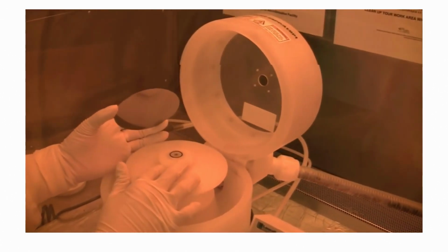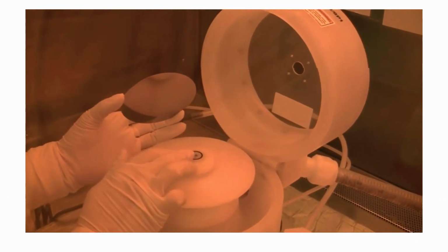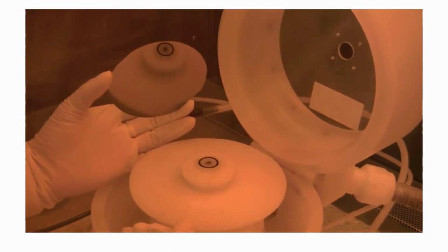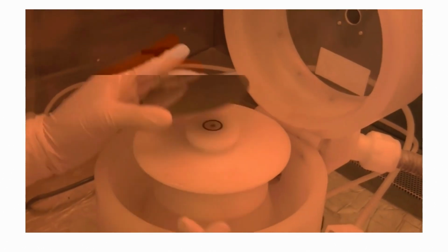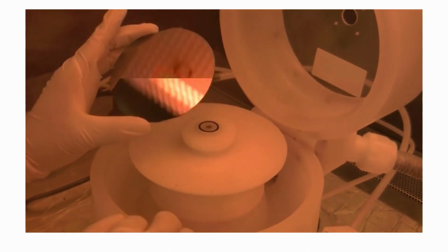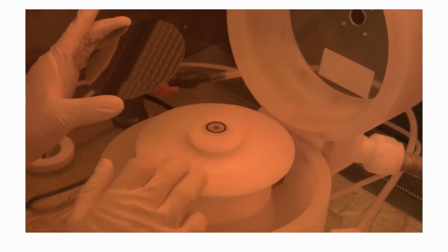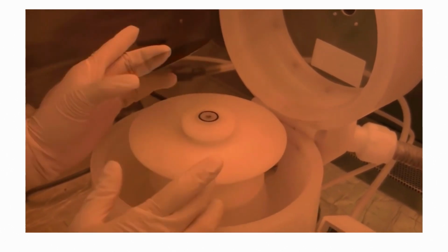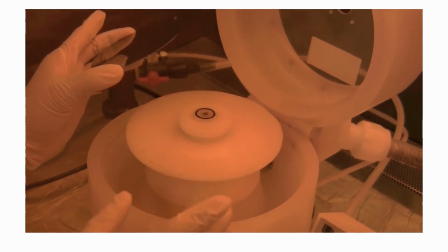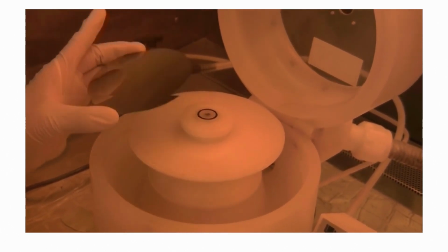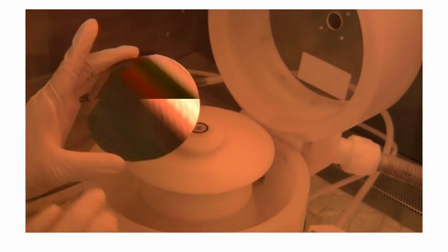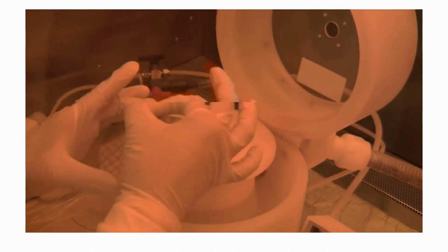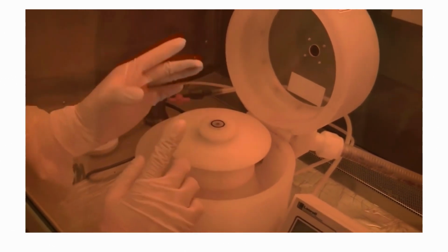So this chuck here has a vacuum in the middle. This vacuum is going to hold the wafer down, so when it spins, the wafer won't fly out. It's very important that your sample is bigger than this chuck. Now if you have a smaller sample than this chuck, that means some air is going to be sucked in around the edges. If that's the case, you must mount your device on a bigger substrate like this. So if I have a small little glass piece, I put it on top of a wafer like this, and then put this on top of here.